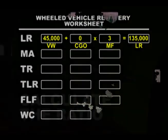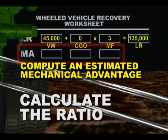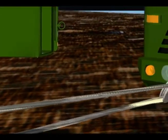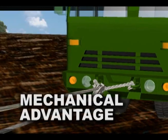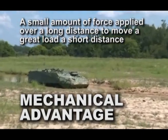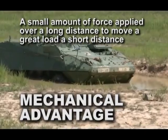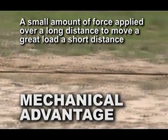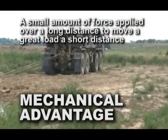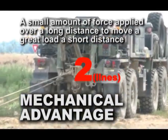The third step of the recovery process is calculate the ratio. This means we need to compute an estimated mechanical advantage required for rigging, line 2 on the recovery worksheet. A mechanical advantage is a small amount of force applied over a long distance to move a great load a short distance. A mechanical advantage is needed whenever the load resistance is greater than the winch capacity. The mechanical advantage of any simple tackle system is equal to the number of winch lines supporting the load. In this example, you will notice a mechanical advantage of 2.